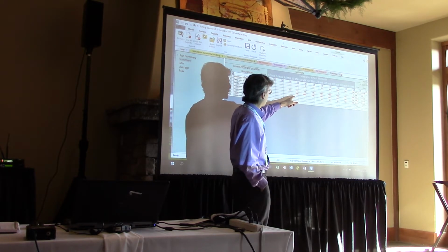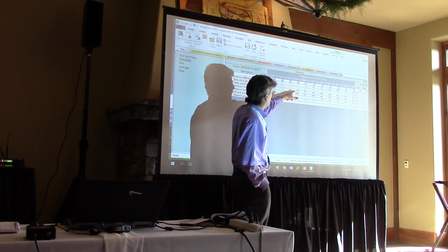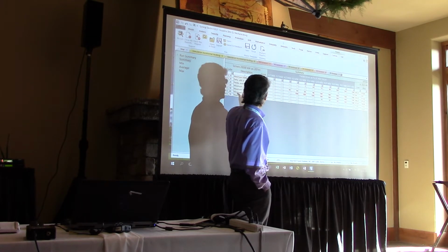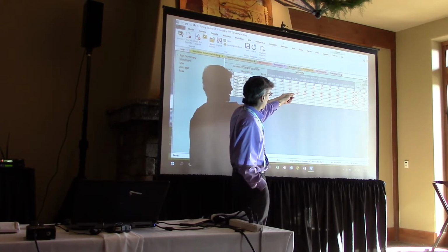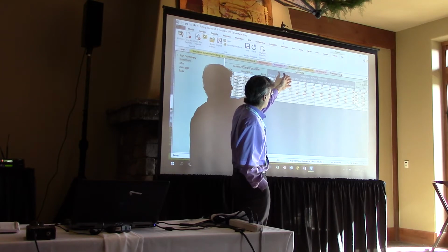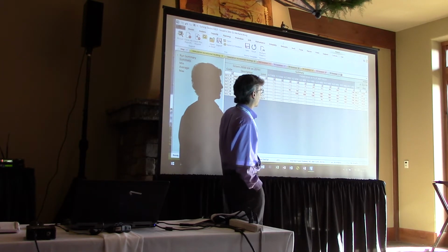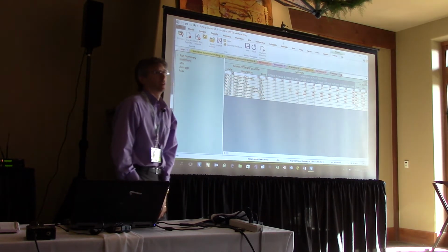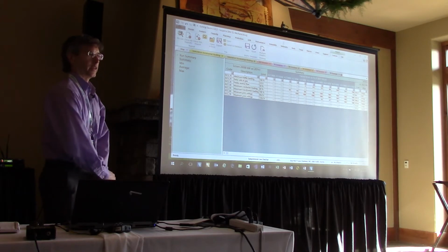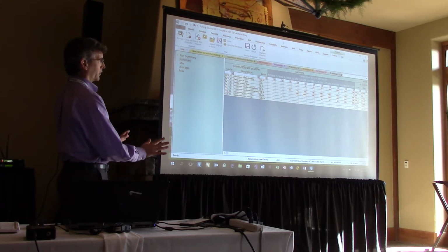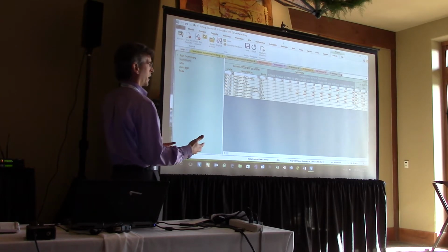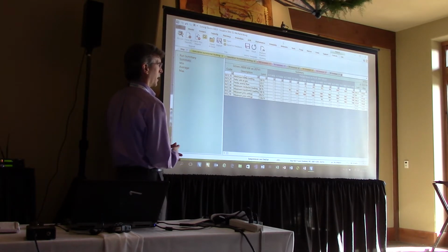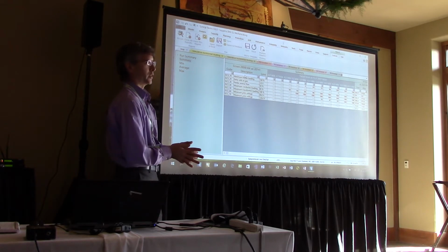But now when we get to 6 megawatts, we've got almost 50% on the screen, and then we've got 100% on conductor loading. So 100% of the time, I've got a problem at 6 megawatts. So, I might say, well, 5 megawatts is the most we're going to put at that location. So that's what we're trying to do with the screener. Make it run fast, make it simple to see, run over time, and present how often, how much of my window I'm going to have problems with this generator.